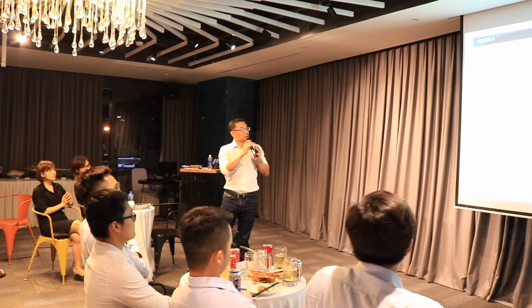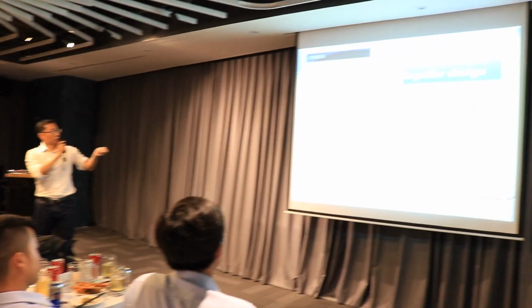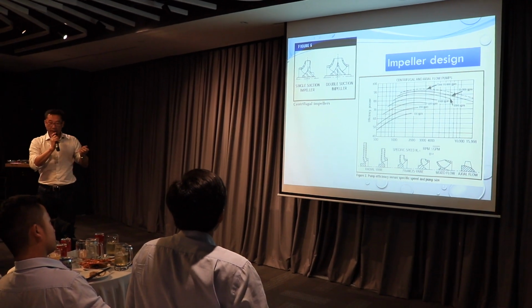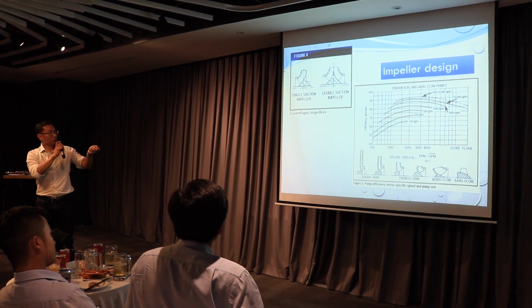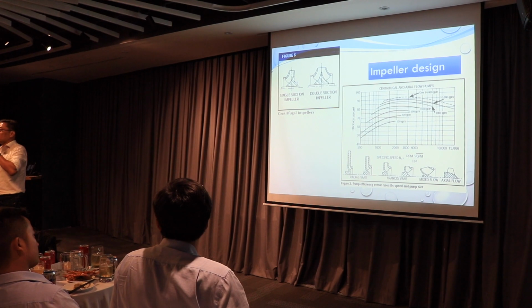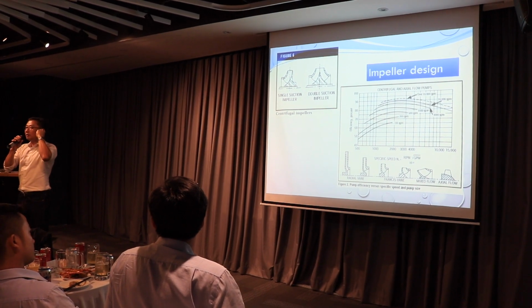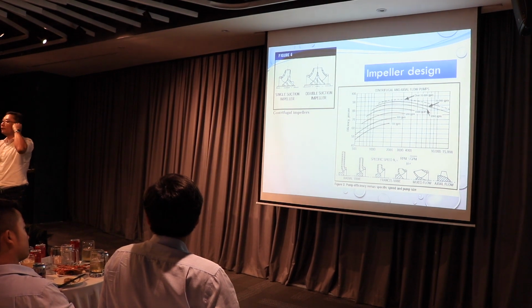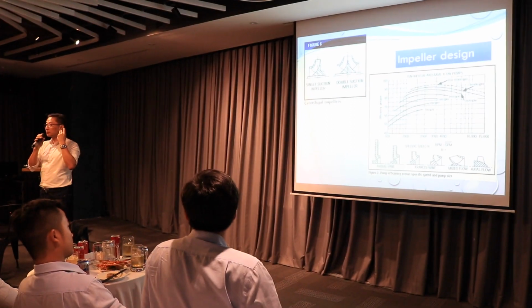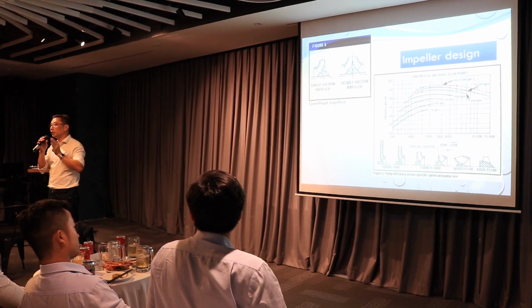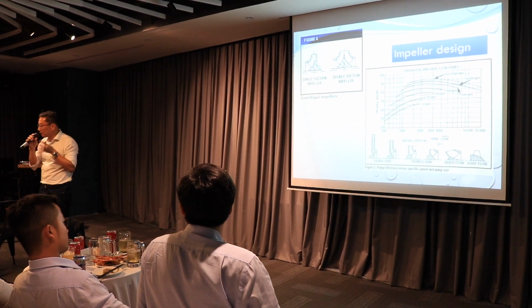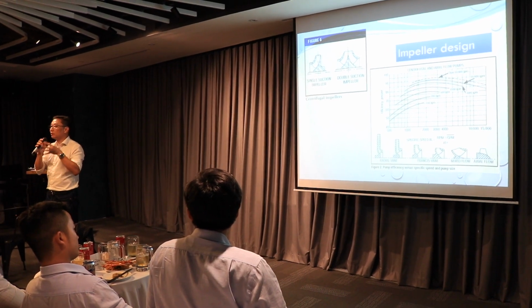Now coming back to this, you see this drawing here is a single volute. The water comes into the eye and comes out the discharge. A split casing is a double volute. That means the water will come in from the left side and the right side. Double the capacity. So sometimes your engineer says, hey, how come the split casing has no flow? Or only 50%? Rotation wrong? Maybe. What else? Or maybe the water going to the suction only goes to one side. That means the piping on the elbow coming to the suction is set up wrongly.